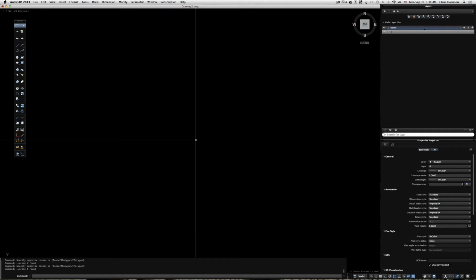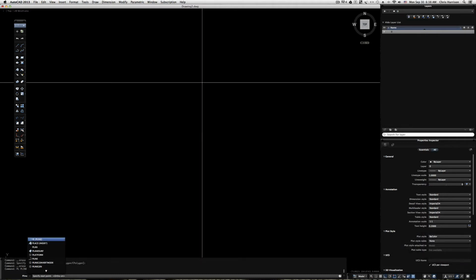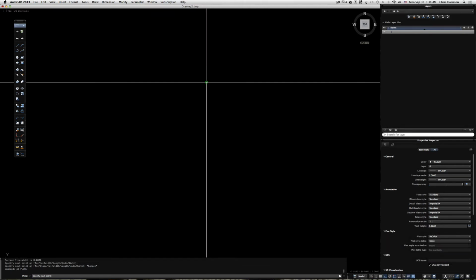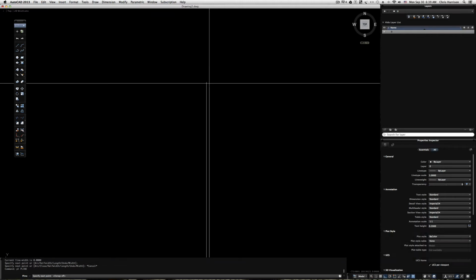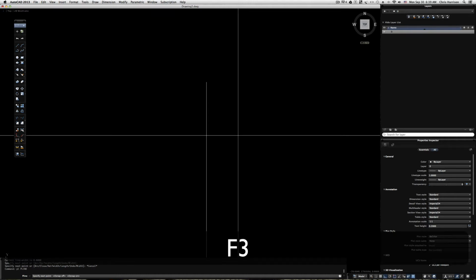Another very useful tool is going to be your mirror tool. So I'm going to draw a straight line here. I'm going to use my ortho. Draw down. I'm going to draw a line out. Now you see I'm able to snap to these points. If you don't see an icon, in this case it looks like a green square up here, your O snap is off. In order to turn on your O snap, you would hit F3. I'm going to select function F3 for me, and when I do that, you notice that those boxes disappear. It's not allowing me to automatically connect to these lines. I'm going to turn that back on, and you'll toggle that on and off constantly. That is something that you'll quickly become accustomed to in working in CAD. So I'm going to turn back on my O snap.